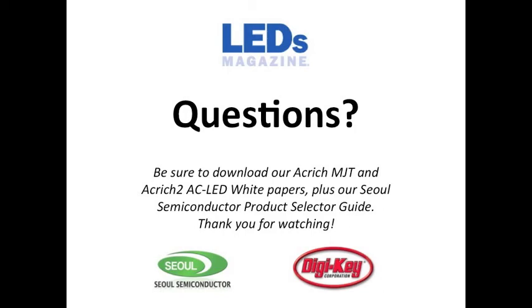Yeah, that's a good question. I don't know if everybody's watched the CEC, but they've just put out a new spec for 90 CRI systems. You can do 90 CRI in most LEDs. It's kind of a change of the phosphor. The drawback there is you're going to get a reduced efficacy in the system.